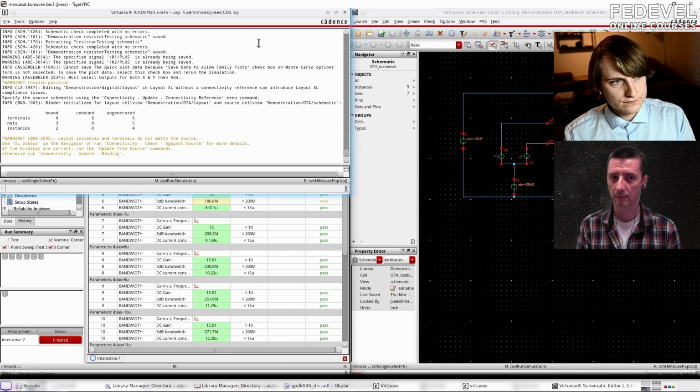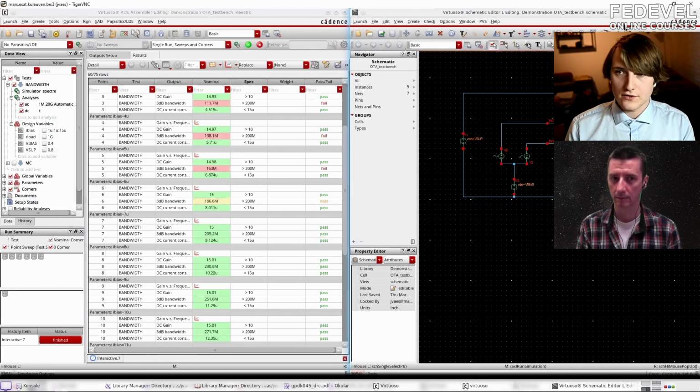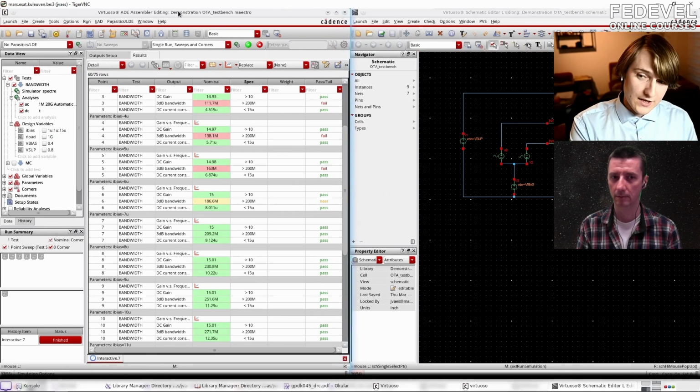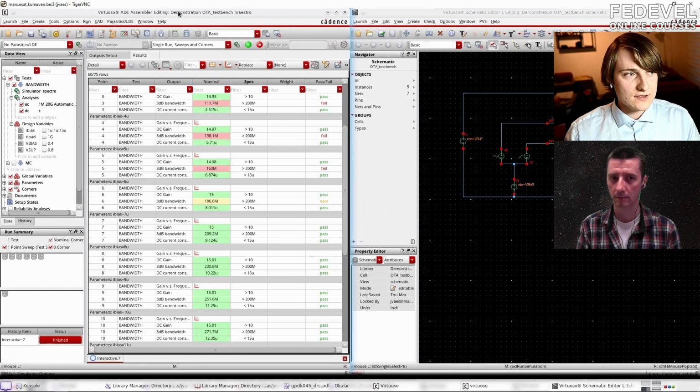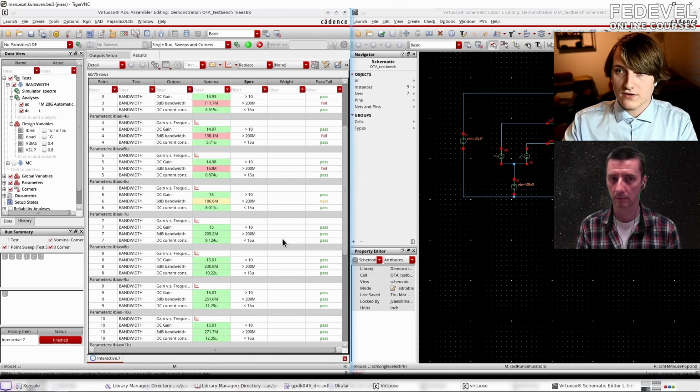Virtuoso is the platform. And then within Virtuoso, you have lots of different things because you have the schematic editor is one tool. The layout editor is another tool. And again, you have different grades. The simulation tool is another tool. And the simulation tool that I run here, so Maestro is what it's called, is different from the simulator engine that is used. So the tool is the thing that here shows me my interface, gives me these functions. The simulator itself is a different thing that runs in the background.